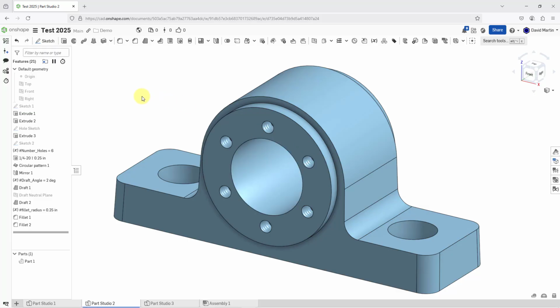And then there is another type in here, and I don't have a good example in this part. Let me go to variable, and here we have assigned. And this is any. And there's a lot that you can do with any. The any kind applies to anything that has a length, an angle, or number. Or maybe you want to use a length with a different unit than what we have in our worksheet. So for example, this worksheet is in inches. I could use length with a meter unit or a millimeter unit.